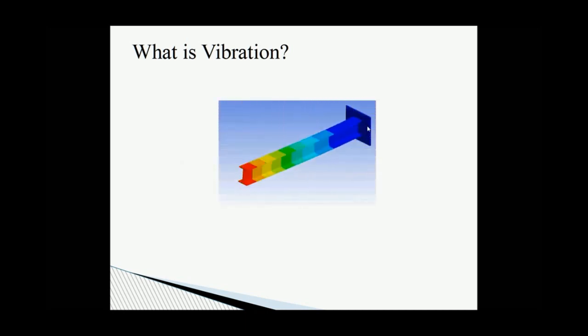Here is the third mode of a cantilever beam. The third mode is a vertical bending mode. Now, modal analysis is very important in determining how your structure or system will react at given frequencies and given amplitudes when vibration is inputted into your system or structure.